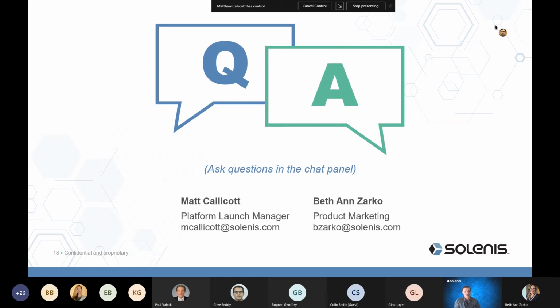Will this work with delayed response in process control? Let me try to clarify that question. Are you asking about system lag? If we have lags in the process and we make too many reactive moves, we could inhibit or increase variation because we're not taking into account this lag or delay. The way the system is set up is to make sure that we are not making moves quicker than the expected impact of those moves.